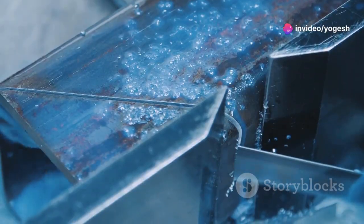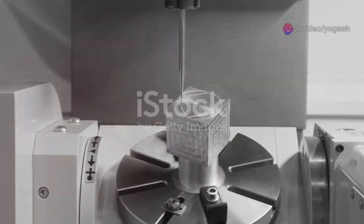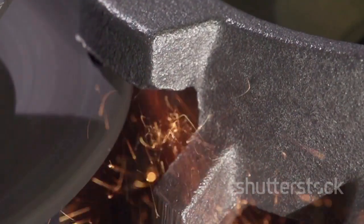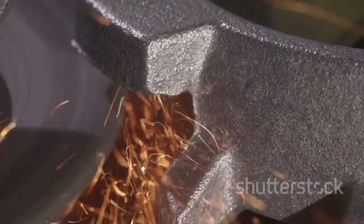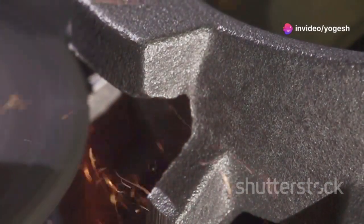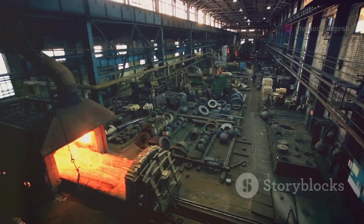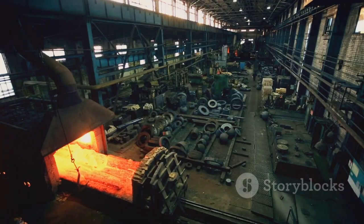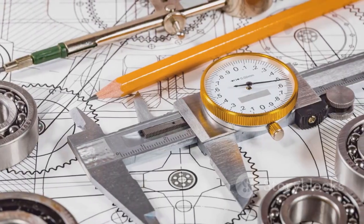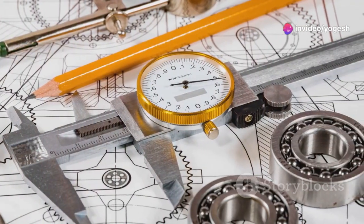Using an entire surface as a datum works for simple machined parts, but not for rough, warped, or oversized components. Castings, forgings, and large sheet metal parts often have uneven or flexible surfaces, making them unreliable as datums. If you try to use these surfaces, the part may rock or sag, leading to inconsistent measurements. Datum targets solve this by specifying exact points, lines, or areas for contact, creating a stable, repeatable reference.